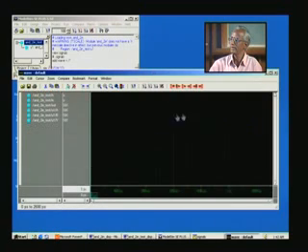Just make it wide enough for looking at the waveform. Now what you have is and2in_test. All of them are the same, except that these three signals pertain to the design. First signal is A, then in. I'm sorry, this is the test bench, not the design. So A, in and then out. You remember we had used in and out in the test bench instead of B and Y, and those are the design. And U1 is the instantiation we had used earlier while instantiating in the test bench, and we call the design module U1.